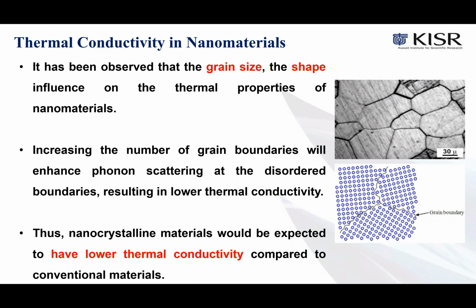Thermodynamic effect. Definitely, nanostructured materials, with their reduced size and consequently high ratio of surface to bulk atoms, show deviation in many thermodynamic properties compared to the same material in bulk. This is because the surface atoms are bound with fewer bonds than the atoms some distance inside.